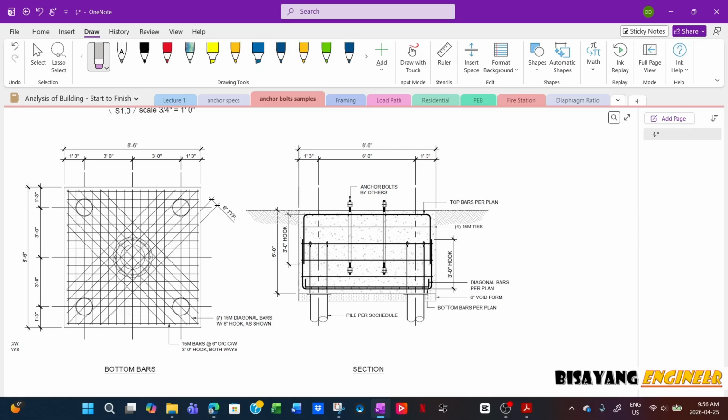The bolts are already in a circular pattern. And then there is a ring plate at the bottom and at the top. The top is more of a template only, and the bottom also serves as a template to make sure that all of these are aligned and vertical. It will also help with regards to the uplift.